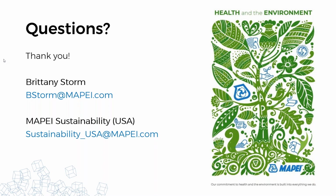LEED does not state a building can't use chemicals like Living Building Challenge does. You often do see red list mentioned on the MR credit for material ingredient reports. However, it's not enough documentation to provide a red list letter under LEED. You have to provide an actual transparency document showing material ingredients.